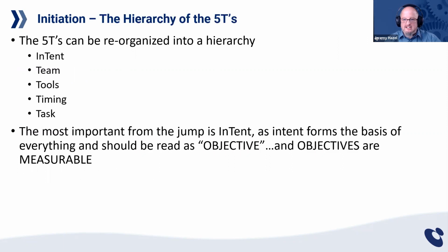Now, this may seem like a subtle thing, but if you don't understand the power in this subtlety, you will not get to the right place. For me, the most important pinnacle of this, the most important step of this is the intent. Here's what I want you to do. In your mind, when you start your FMEA, I want you to replace intent with objective.